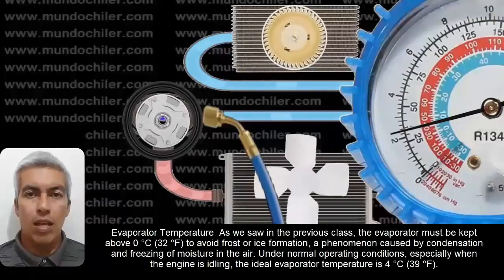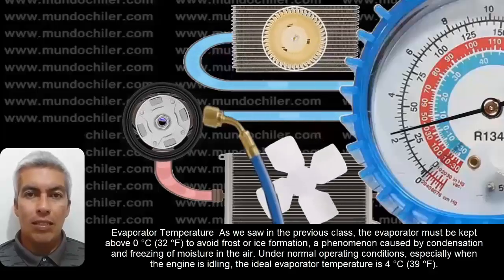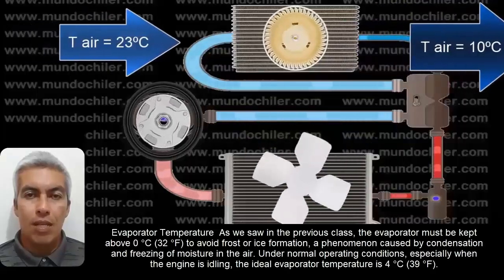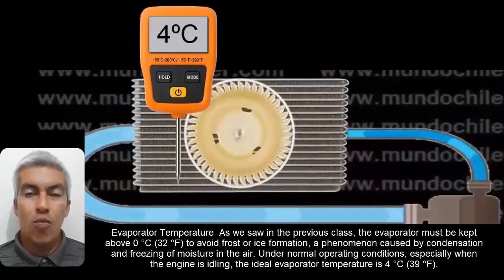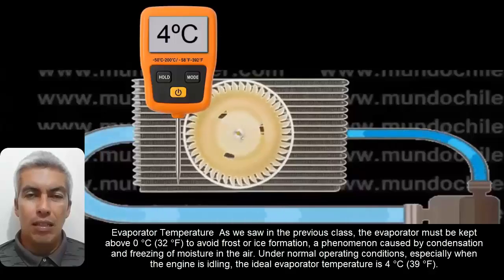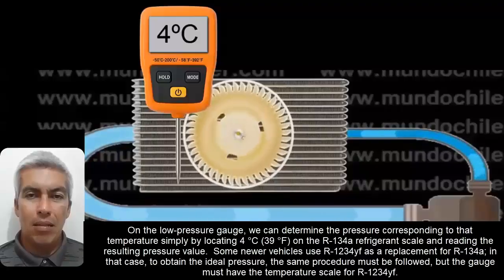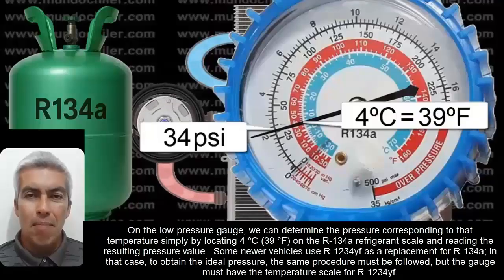Evaporator temperature. As we saw in the previous class, the evaporator must be kept above 0 degrees Celsius, 32 degrees Fahrenheit, to avoid frost or ice formation, a phenomenon caused by condensation and freezing of moisture in the air. Under normal operating conditions, especially when the engine is idling, the ideal evaporator temperature is 4 degrees Celsius, 39 degrees Fahrenheit. On the low-pressure gauge, we can determine the pressure corresponding to that temperature simply by locating 4 degrees Celsius, 39 degrees Fahrenheit, on the R134A refrigerant scale and reading the resulting pressure value.